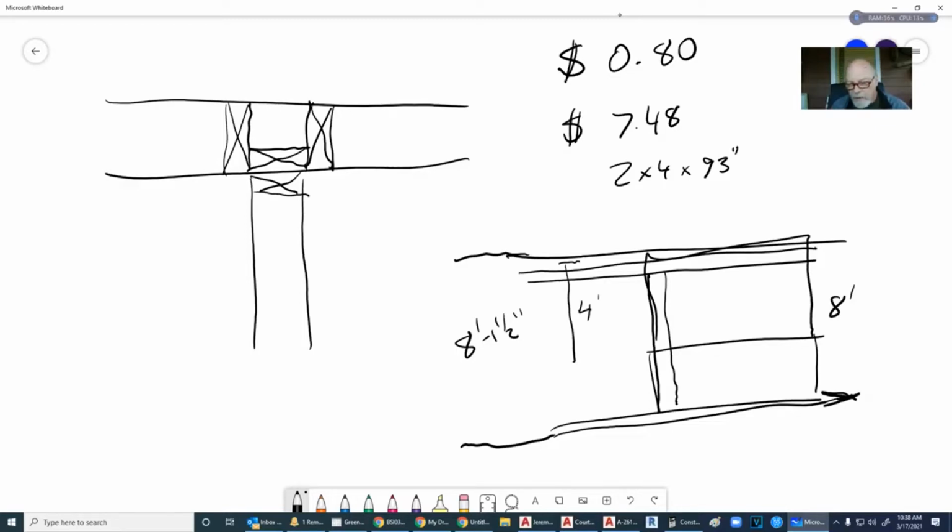But then if you put a 3/4 inch hardwood floor on it, then that leaves you with about a quarter when you're all said and done. Or carpet. Yeah, if you put carpet on it, then you've got a lot more space down here, about an inch. So this is a bad idea because they put that sheathing on, and then this space here, we can't get insulation into it.